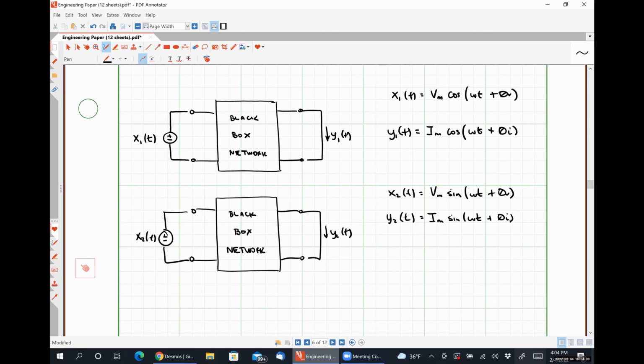All right, I'm getting crickets. So the homogeneity property of linearity states that if you scale the input by a non-time varying amount, the output scales by that same amount. So if we have a system and we apply a voltage of 2 volts and see that the current at the output is 1 amp, if we apply a voltage of 4 volts, we should expect the current at the output to increase to 2 amps. So we scaled the input by a factor of 2, we scaled the output by a factor of 2. We did lots and lots of problems working that stuff out when we were talking about the concepts of superposition and linearity.